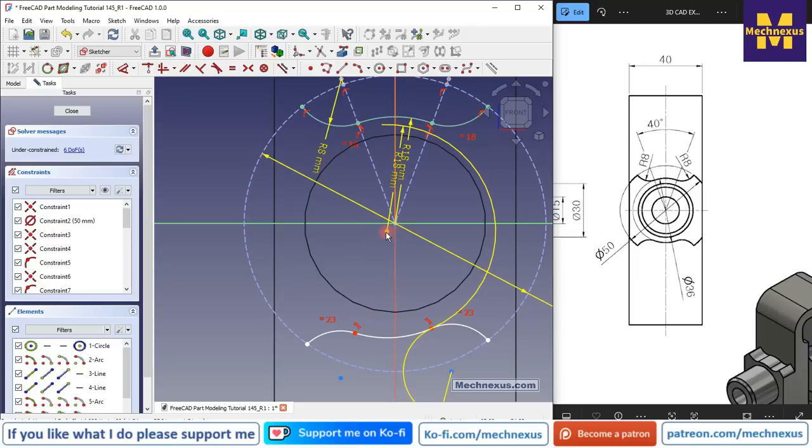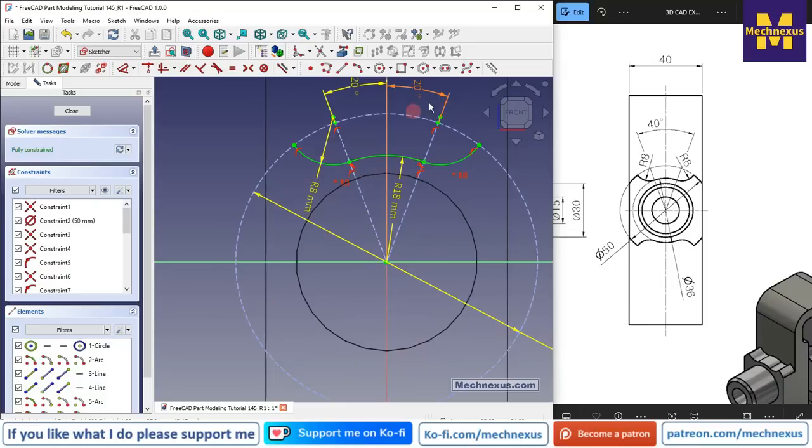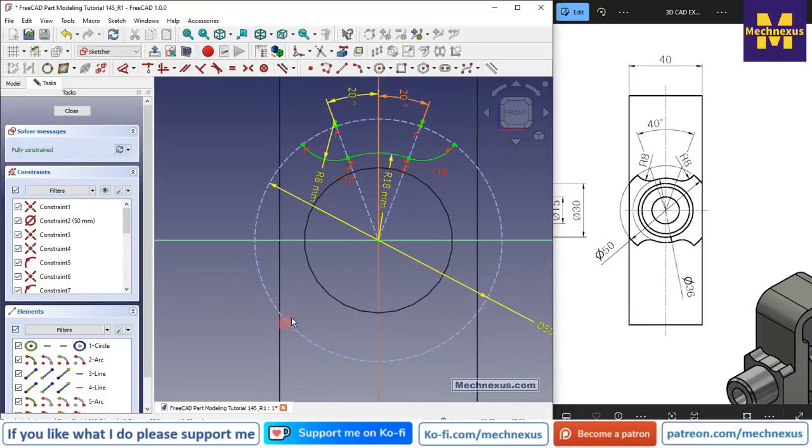So we need to add coincidences if we are using the mirror tool. As of now, this is a problem with the FreeCAD mirror tool, until FreeCAD also applies the constraints apart from mirroring the profile. So because of this issue, we will create our profile from scratch like we have created on this side.